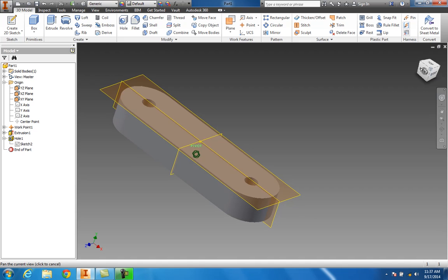Okay? Now at this point we are getting ready to put another aspect onto this, and it's like a 1/2 of a circle, a radius arc up here. And what you do is come over here, click on this plane because it's right in the center. Remember we put that work point, it's where we hinged all this drawing off of.